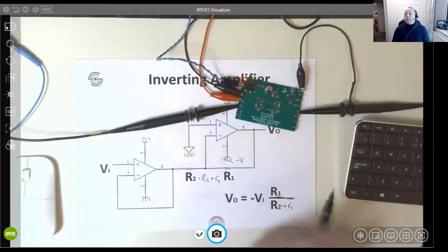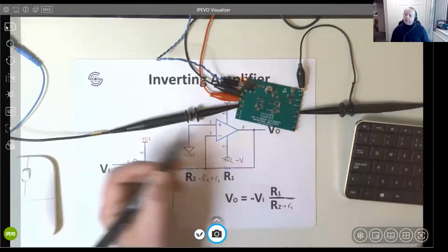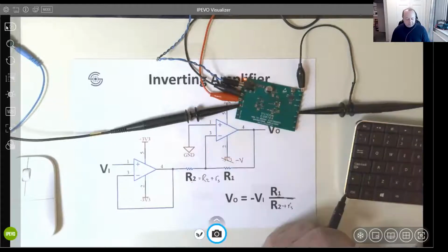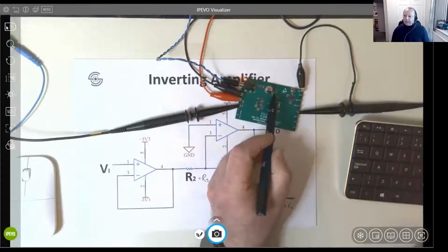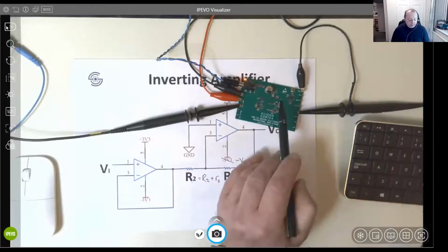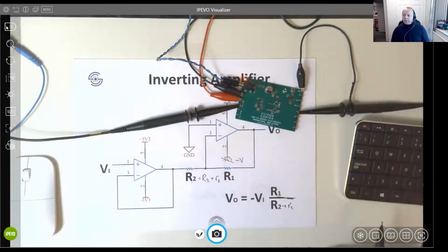So you can't overload them. You won't be able to draw lots and lots of current from an inverter, certainly not this small, like you can from the positive supply rail. But if you're just running op amps and creating a reference voltage, as I've got a tiny one running here, then go to my Silicon Cortex website, to downloads, and download the section on power supplies, particularly the schematic. You'll find the design in there for creating this minus voltage just from an ordinary plus voltage power supply.